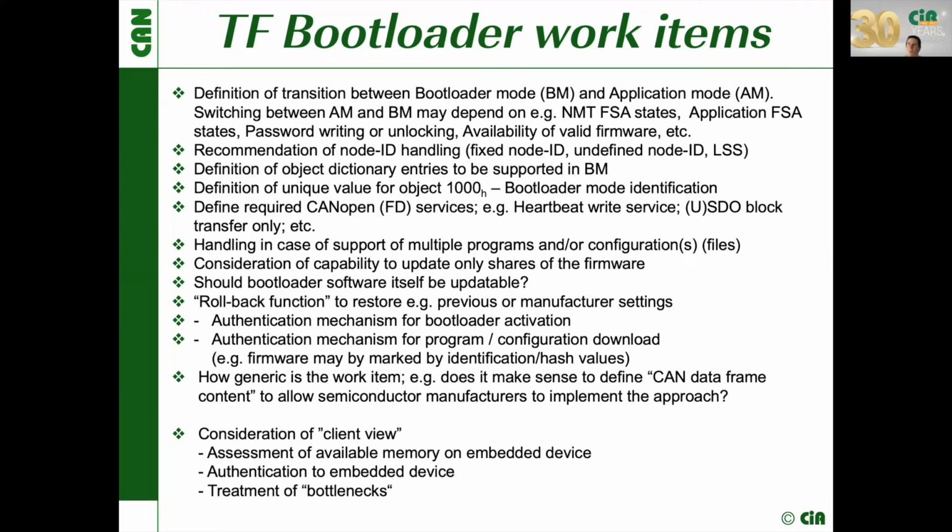LSS. It is a critical task to define which parameters, respectively, which CANopen device functionalities shall be supported in application mode and in bootloader mode, how to identify the devices in bootloader mode, object 1000. This we are discussing, which kind of CANopen services shall be supported. What about the handling of multiple programs? It's not necessarily the case that there's just one.